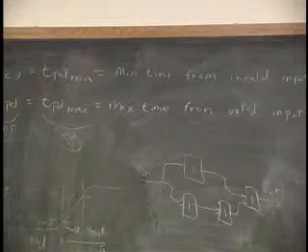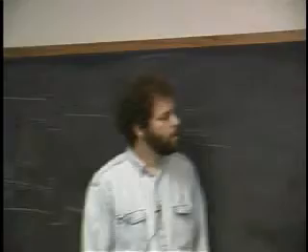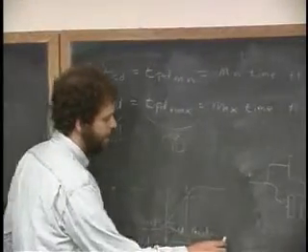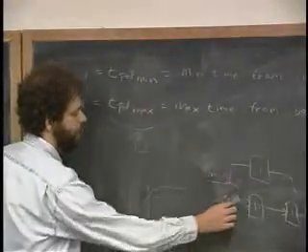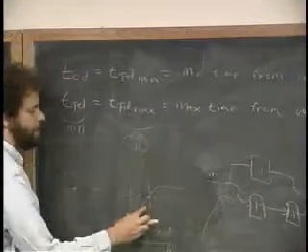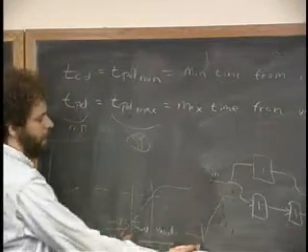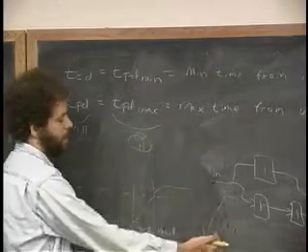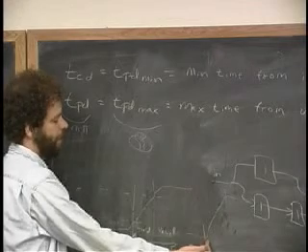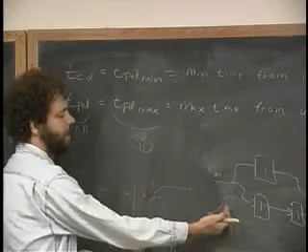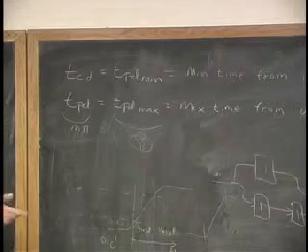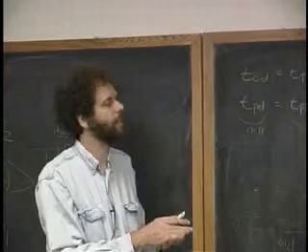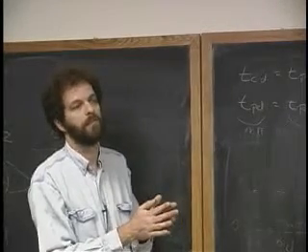Don't we have to get the new valid data in before we can get to the end of the TPD? Well, but at the same time, if this is the in and this is the out, and the amount of time they spend in this regime is the same, then measuring from here to here and measuring from here to here would not necessarily give you different times. From invalid in to invalid out, from valid in to valid out may in fact give you the same time. But there is this business where we're measuring the shortest time it'll take and the most time it'll take. So in general, TPD max will be bigger than TPD min.